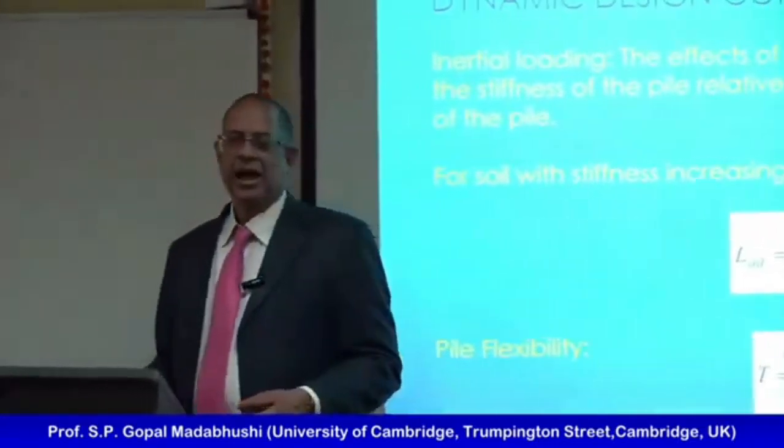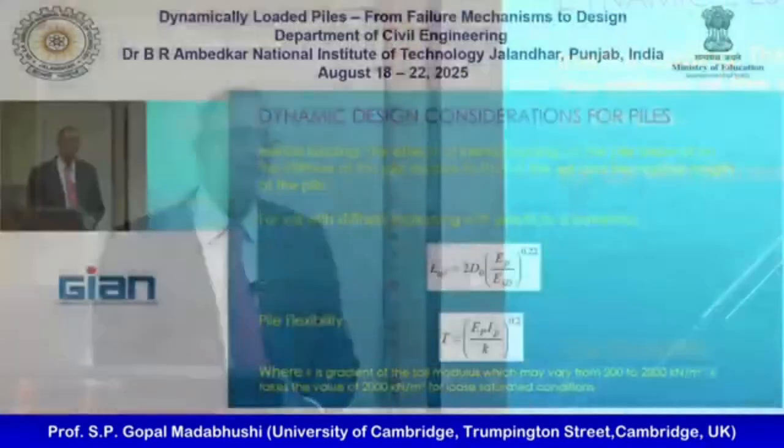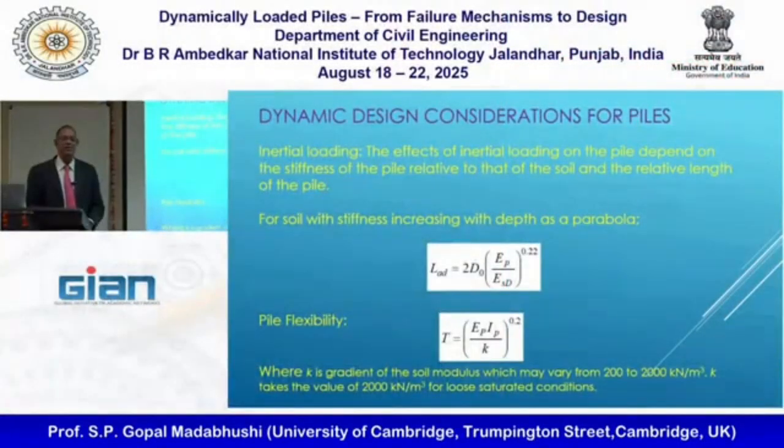What is it? I've been in soil mechanics for nearly 40 years now. What is Young's modulus of soil? This is not steel, this is not concrete. Soil doesn't have a Young's modulus, let alone one measured at one pile diameter below ground. Say it's a half a meter diameter pile, you're looking for the vertical stress half a meter below ground, which is tiny, and you're trying to say, oh, I want to know the Young's modulus. There is no such thing. So this is a stupid thing that numerical people have.